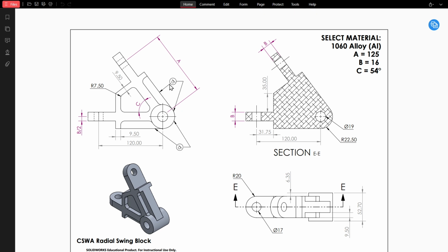You may also notice that we have these strange symbols. This means that the relations here are tangential. So when you make a line from the circle, it has to be tangential from here. But also we have to factor in that the circle and the line here is also parallel to this line. There's an invisible center line, so it means that we're going to be having two relations here. One that's parallel first, then it's tangential. Remember, parallel this line to this line, then make it tangential to this circle.